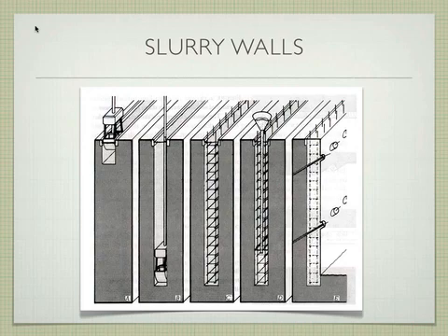Okay, this is out of your book, so you can reference this later on. Then you put your steel reinforcing in. Then you use this tool that's called a tremie, which is like a giant funnel with a really long neck. This sticks all the way down into the bottom of your foundation. I should say, as this happens, I should back up. This is what this little line is.